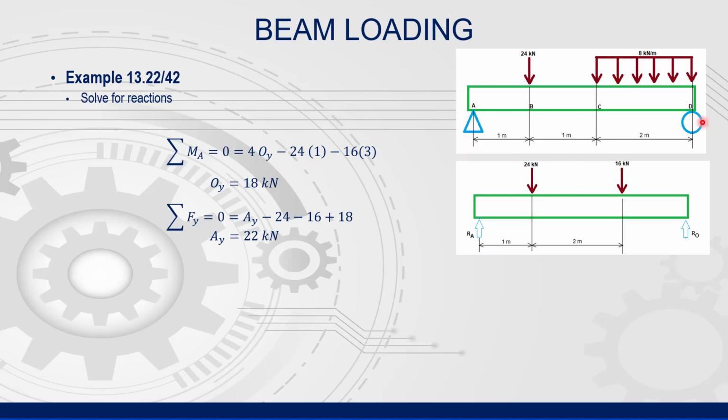The opposite end of a simply supported beam has a roller support. This support prevents vertical translation, but allows movement in the side-to-side direction. Thus, as the beam deflects in the middle, the right-hand side pulls inward. This constraint is represented by a circle on the right-hand side.